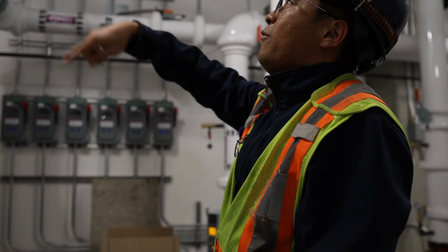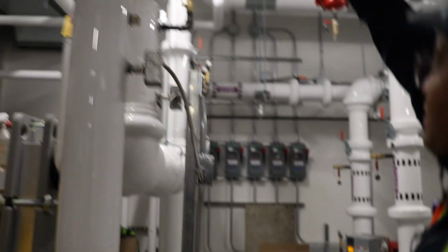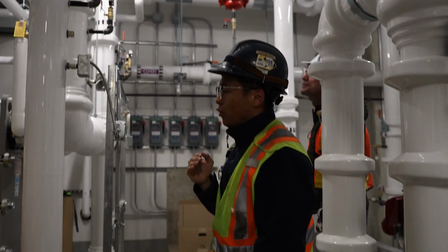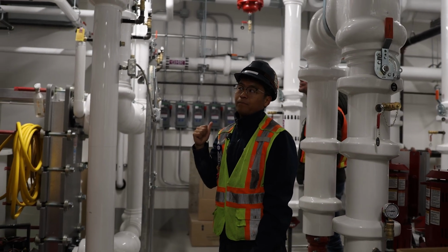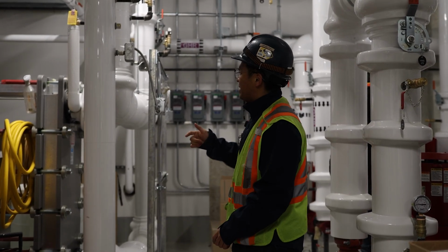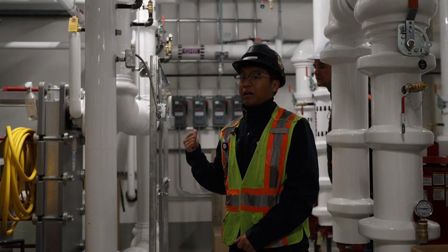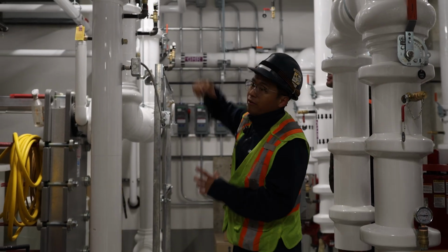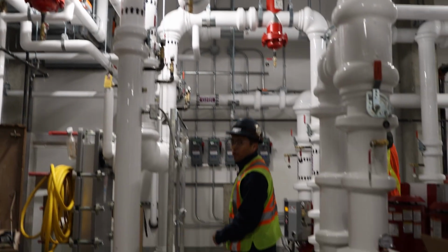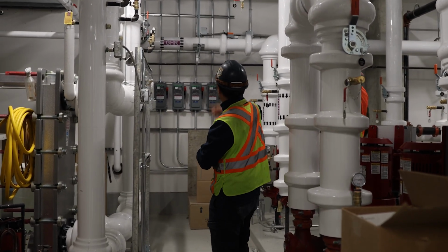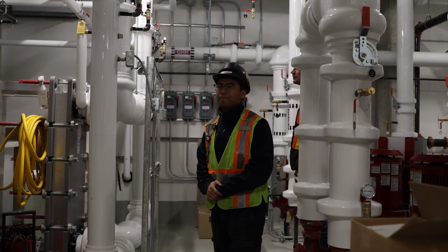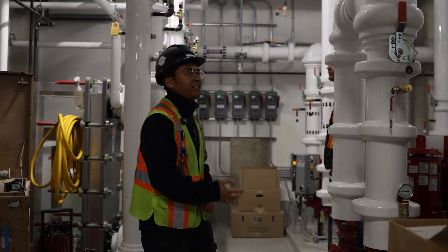We also have a 3-way valve right here. This 3-way valve for heat exchanger 3 modulates to maintain the supply temperature of HRV1. If the HRV1 supply temperature is calling for heat, this valve will open more, so we give more heat to heat exchanger 3, and the pump is running at constant speed. It does the flow to the heating coil to maintain the supply temperature. Any questions?